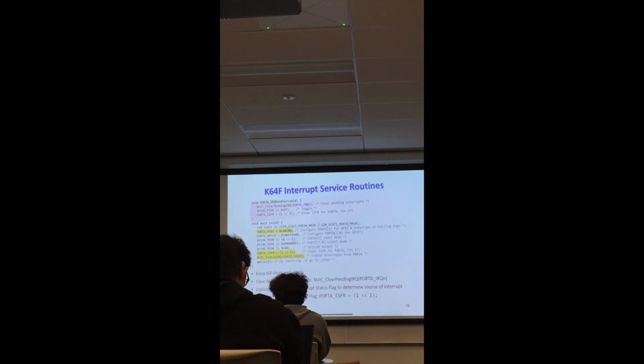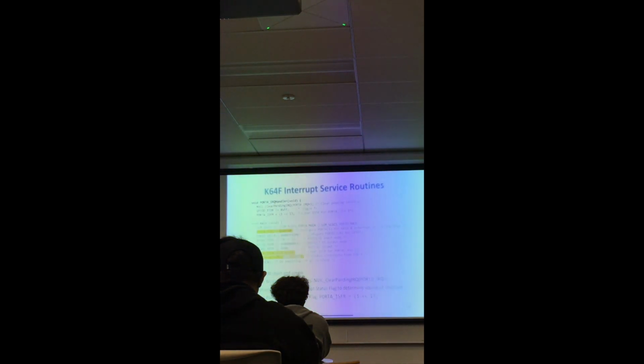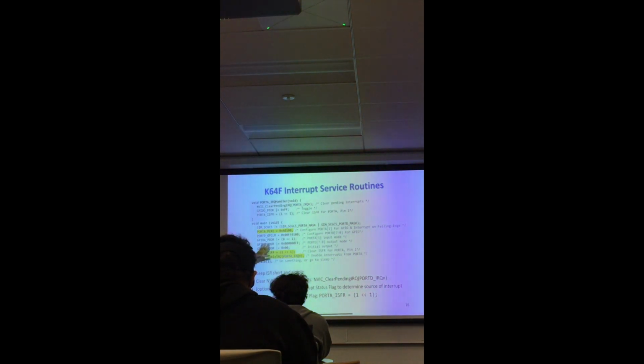So if you want to modify or reconfigure interrupts during runtime, make sure that you stop or disable all interrupts. In other words, NVIC, which stands for Nested Vectored Interrupt Controller, has a command to disable all interrupts. In my slides I have that command, disable IRQ, with underscores.